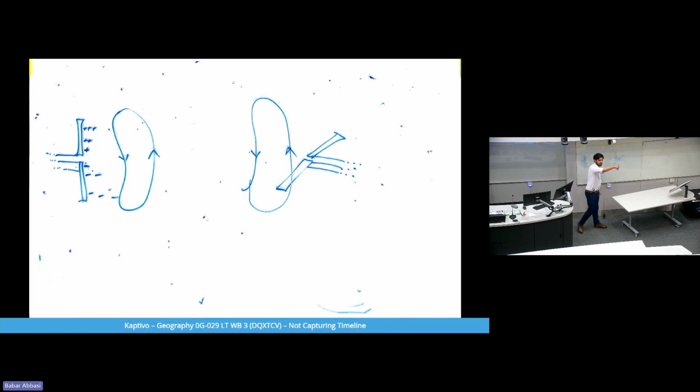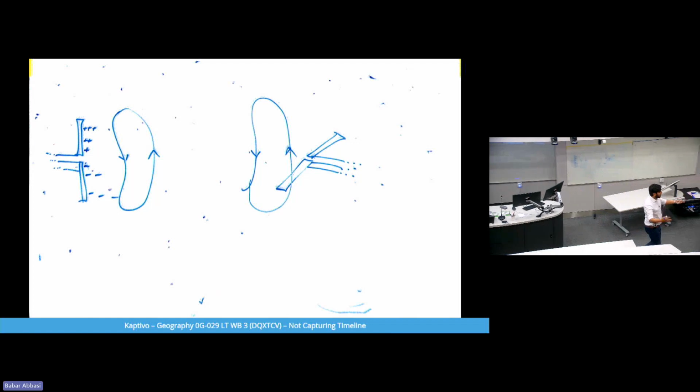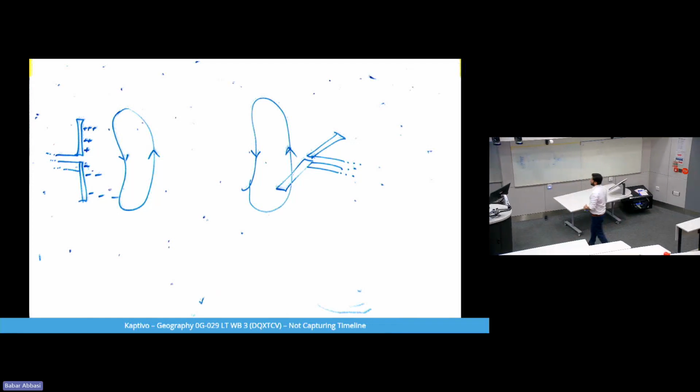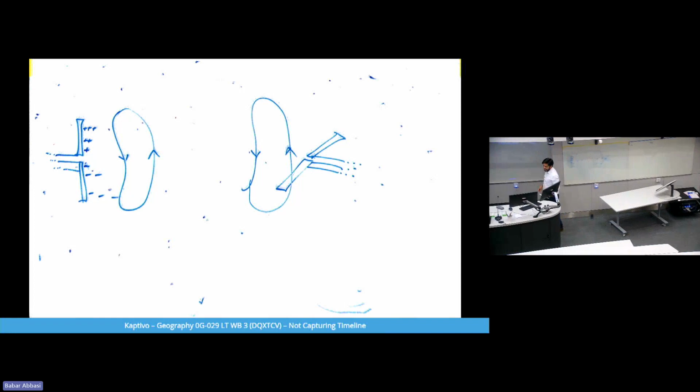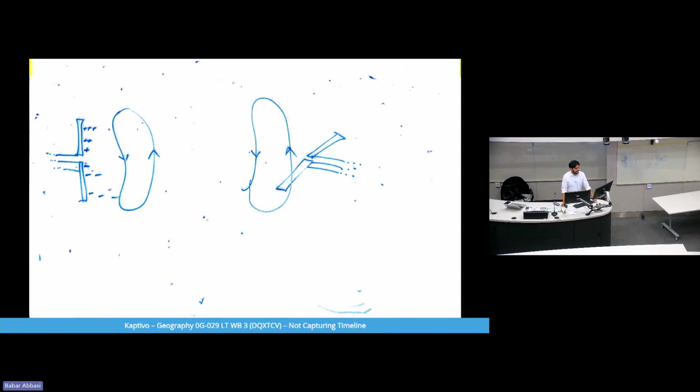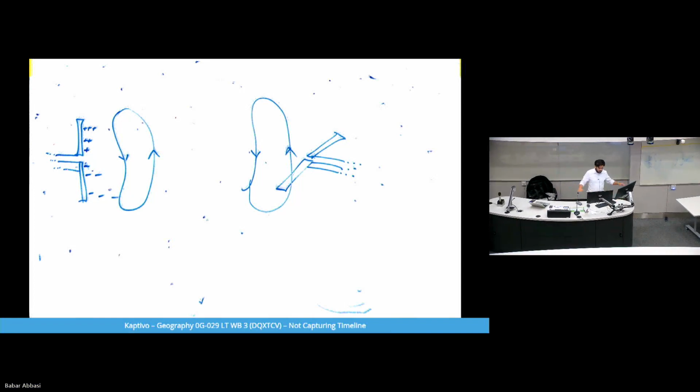So the electric field is oscillating with respect to time in this direction, but my dipole is in this direction, so it will not receive anything. Okay, so this concept is generally translated as simple polarization. So what I've just shown you is two linearly polarized antennas, and they are oriented perpendicularly to each other, so that's why they are not going to receive any energy.